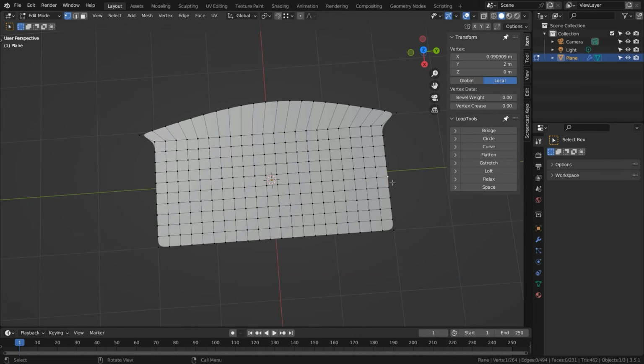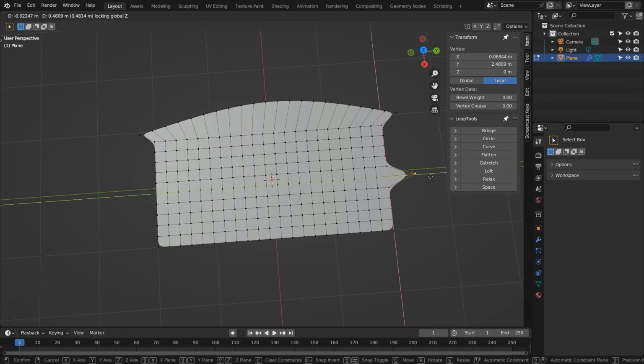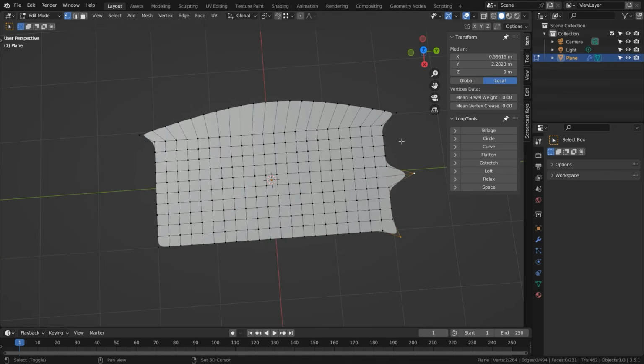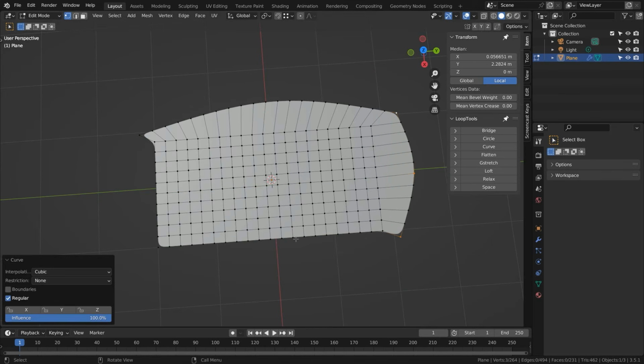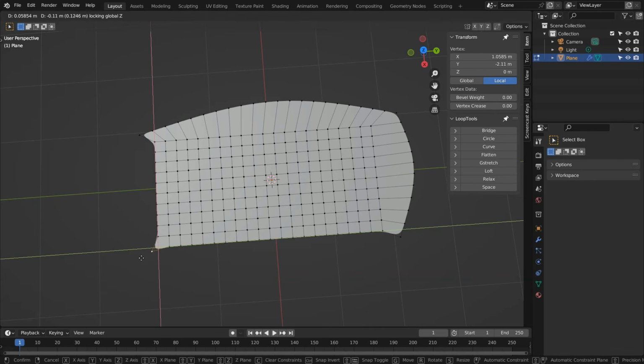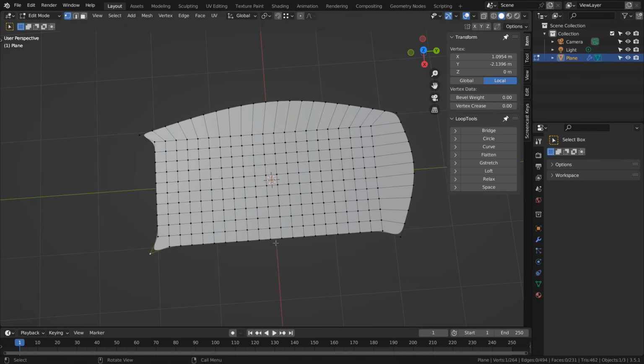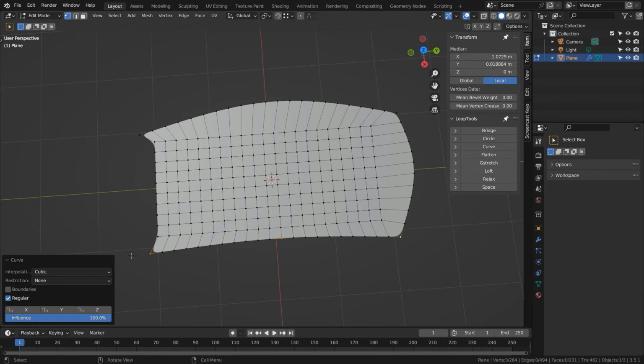I'll just move a point out near the middle a little. I'll move the one at the bottom corner, just for the sake of it. Select these 3 points and press curve again to make this curved edge. Maybe I'll just move the other corner at the other side and just select 3 points which will describe my curve at the bottom. I'll add a final curve at the side here just so everything flows. Select these 3 points and press curve.